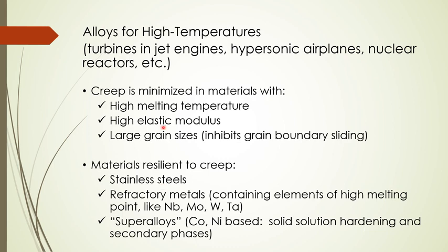We can minimize the creep effect on materials by using materials that have high elastic modulus, or high melting temperature, or materials with a large grain size.